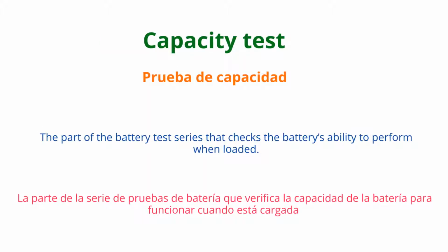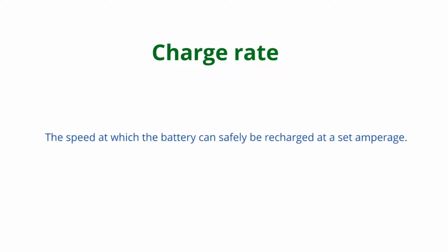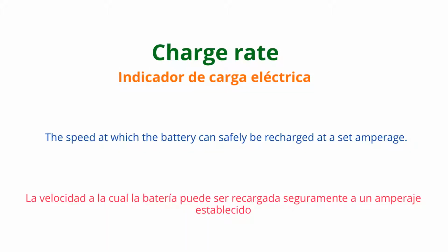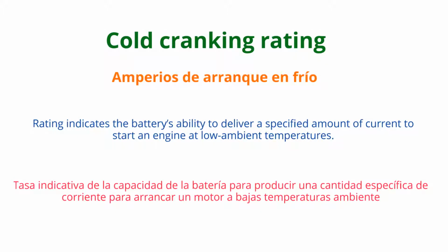Capacity test. The part of the battery test series that checks the battery's ability to perform when loaded. Charge. To pass an electric current through a battery in an opposite direction than during discharge. Charge rate. The speed at which the battery can safely be recharged at a set amperage. Cold cranking rating. Rating indicates the battery's ability to deliver a specified amount of current to start an engine at low ambient temperatures.